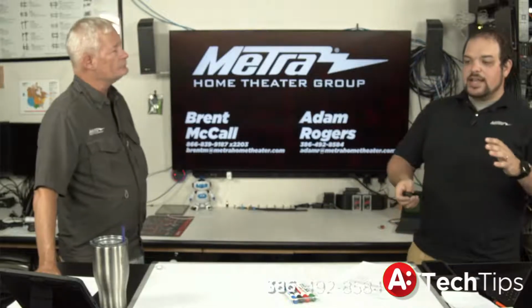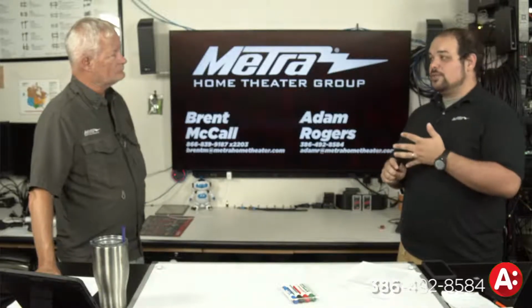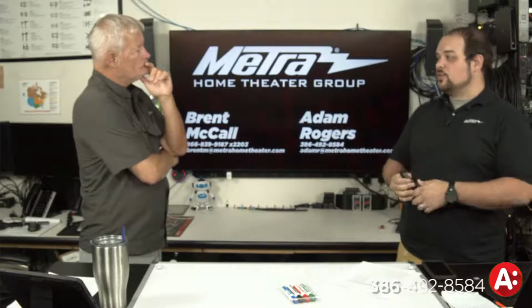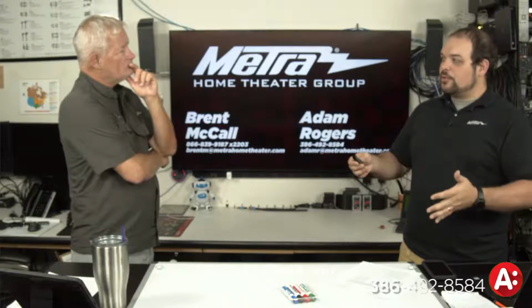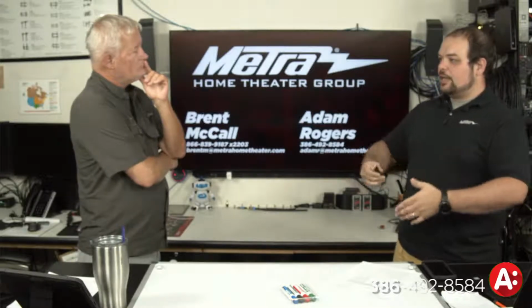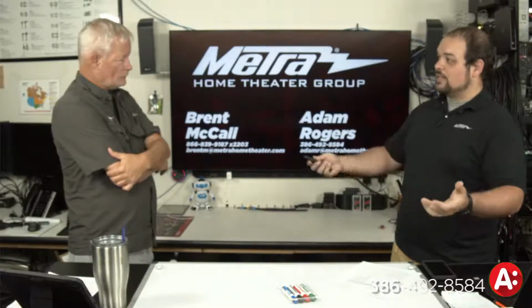Correct, yep. This is used a lot in network devices. We have wireless access points. We have IP cameras. We now also have different types of displays. Someone like Control4 with their touch panels, they're all Poe powered. They also can be powered locally, of course, which is a nice feature. Now, one of the big questions that we get a lot is when people call in and ask, what kind of Poe are your cameras? That's a really good question because you need to know that going forward in order to have the correct type of Poe device.